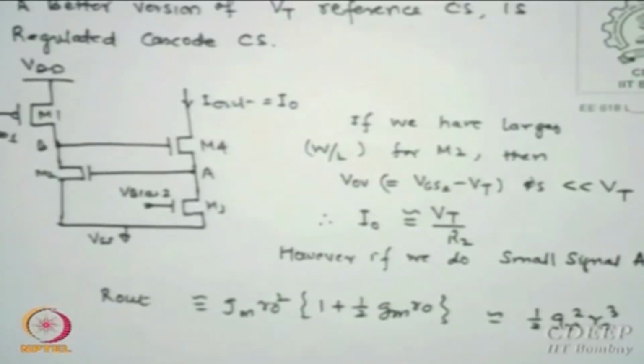And therefore semiconductor resistances have negative TCRs, typically 2000, 3000 ppm per degree centigrade. Like an N plus transistor source, if you use it, it is around 3000. If you use a poly doped resistor, it can be 2000. So is that point clear? So resistors in semiconductors have negative temperature coefficients, and that is sometimes advantageous, sometimes a disadvantage, because both negative may add, or if the other quantity is positive, it may actually subtract.